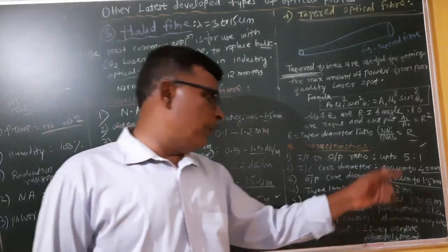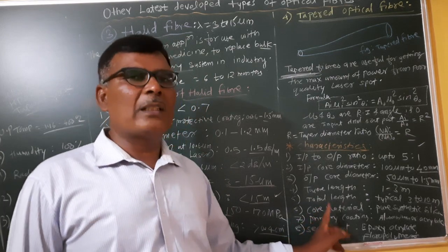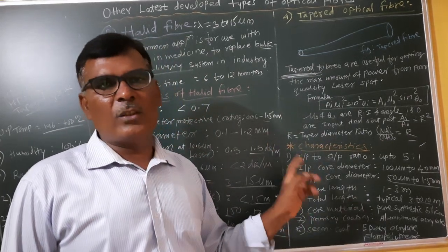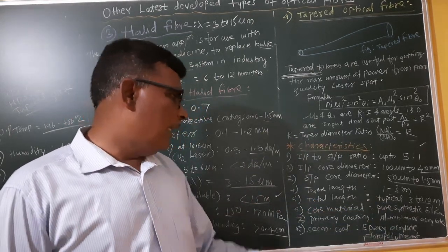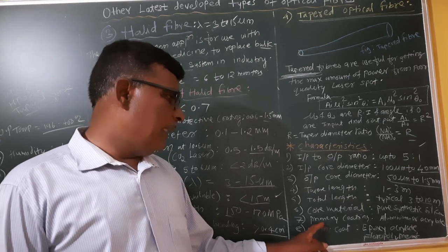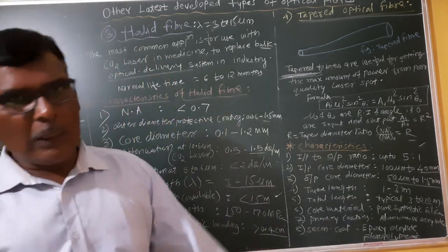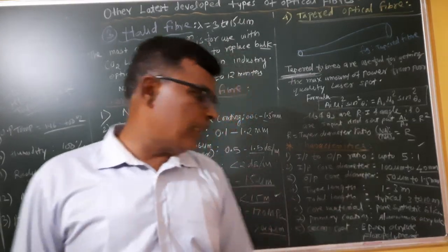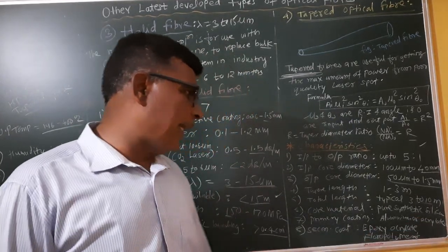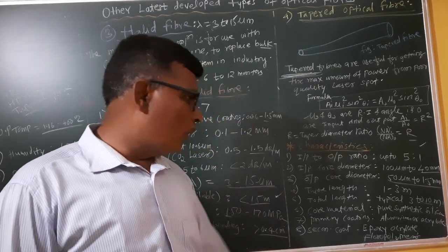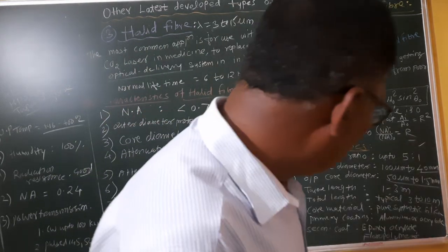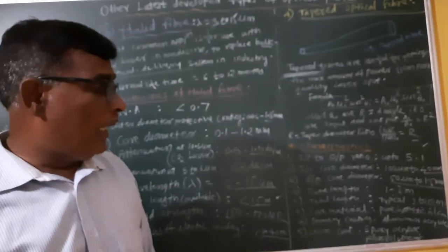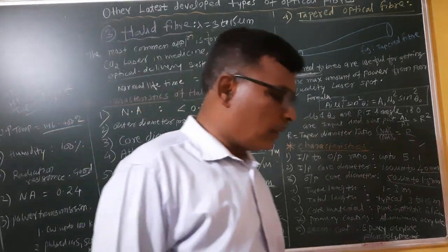And the core material is pure synthetic silica. As we remembered last time, for HPSIR and HPSUV the core material is doped silica. Here we have to say that pure synthetic silica is the core material. And then the primary coating is aluminum, as last time, and polymer. Here aluminum and acrylate are used. And the secondary coating is epoxy acrylate or fluoropolymers and epoxy acrylates. These are the secondary coatings used for such type of fiber.